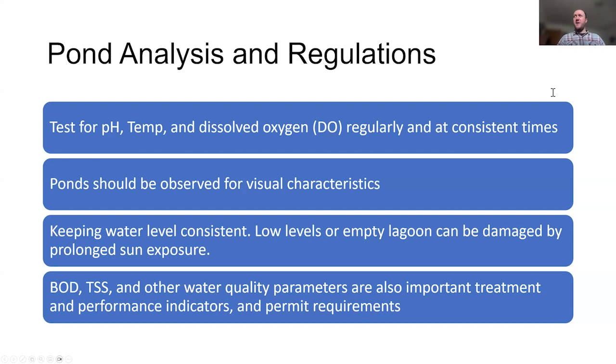And then Brenda, your comment about having 2 feet of freeboard. I think that is a requirement with pretty much all lagoons. 2 feet is what I've heard. It could vary a little bit depending on who your regulatory agency is, but it's really important so you don't have overflows. The lagoon in that first picture has a pipe going out at about 2 feet. If it gets up to that point, it will flow out of that pipe as opposed to overflowing the lagoon.